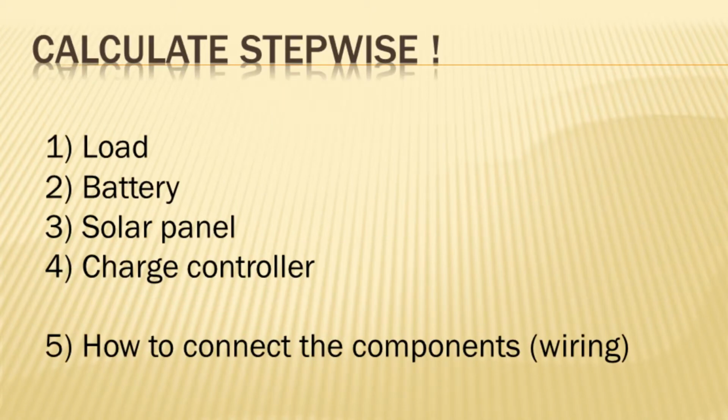And when I calculate my systems, I typically do it stepwise. And first of all, I always consider the load. Then second, the battery. Third, the solar panel, and so forth. And only in the end, I consider how to connect the components or how the wiring should be.